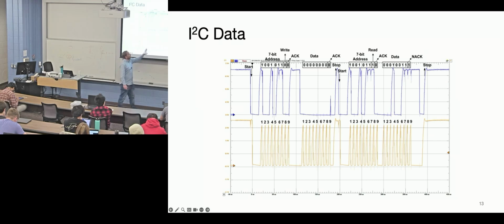So you can write an address and then data, and these can happen right after each other. The hardware should be able to respond quickly to that. It's just if there's an extra task, you might have to wait for that. So the programmer sets the time frames so that it matches the slowest. This is not like Ethernet where all that timing and protocol stuff is baked in. You have to fully understand what the target's doing.